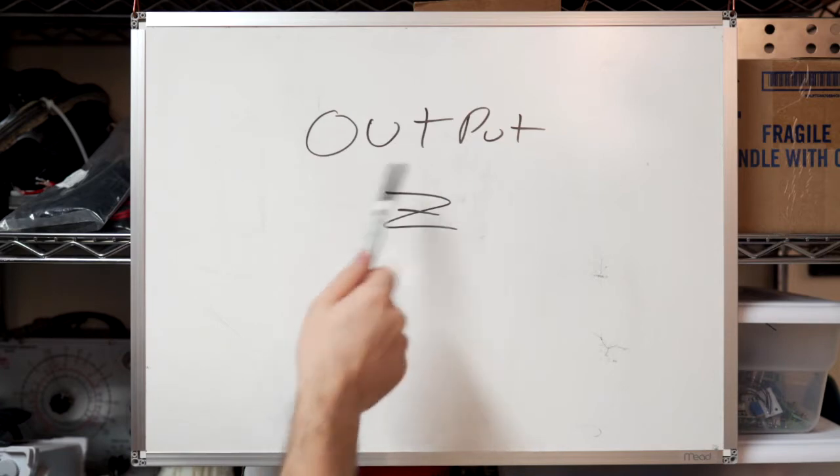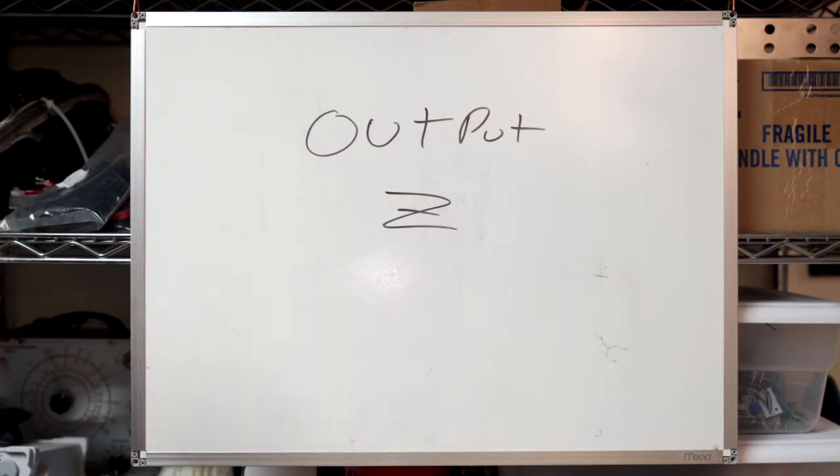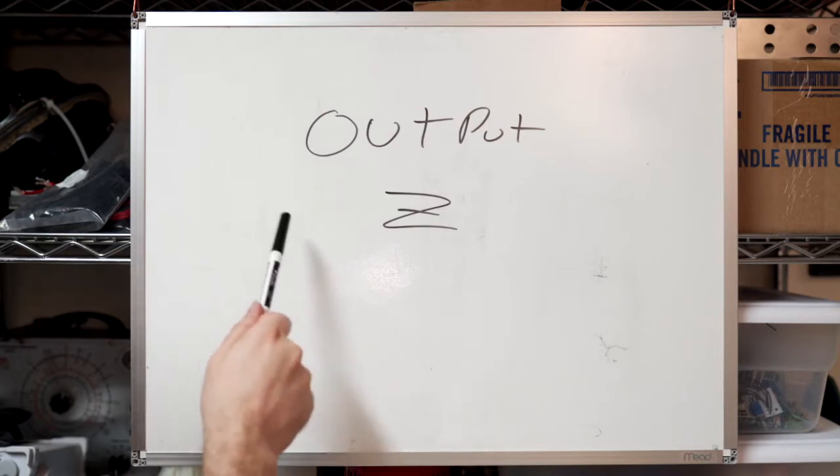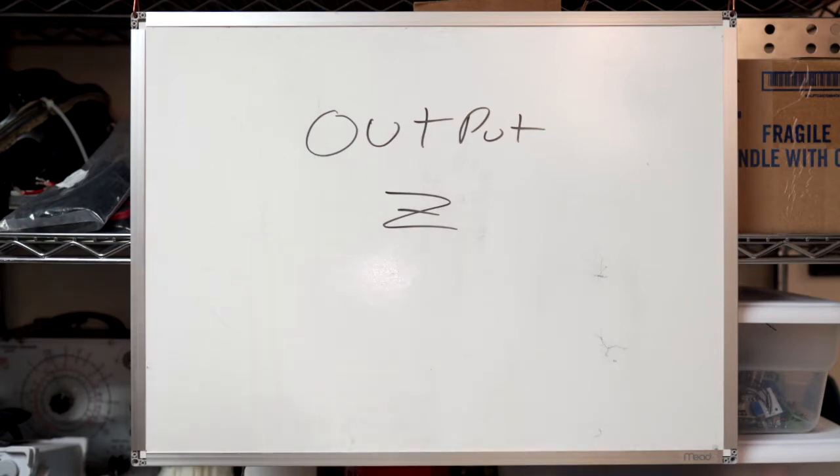Impedance, Z meaning impedance, and if you're not familiar with it, is just like resistance, only it's frequency dependent. So if your device, or the thing that you're measuring, changes its resistance depending on the frequency that you're measuring at, then it doesn't have a resistance, it has an impedance. So that's what we're talking about.